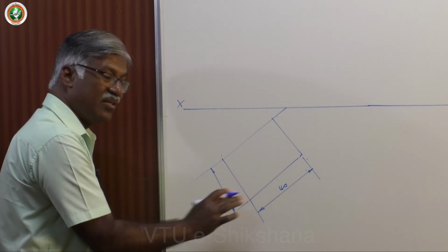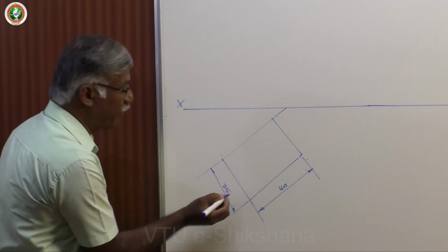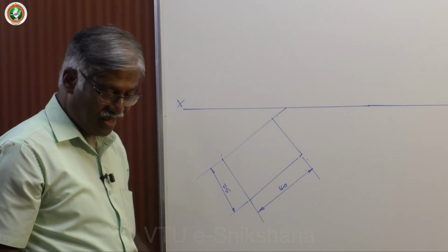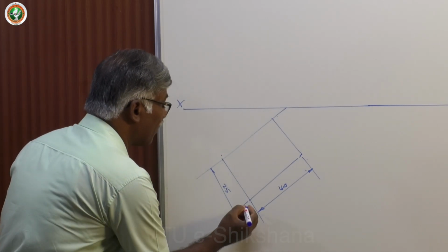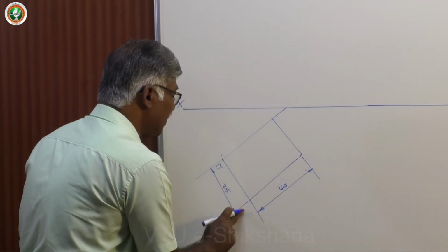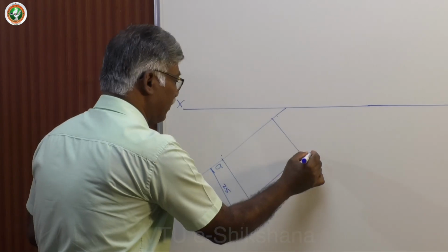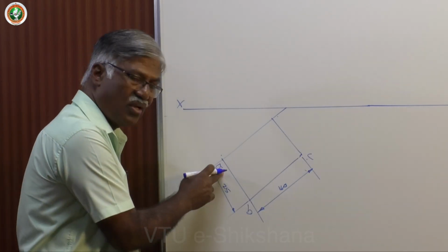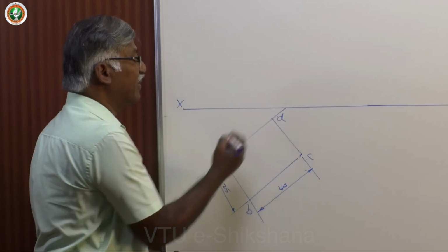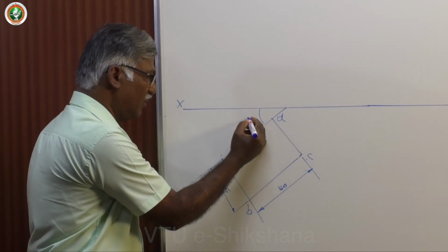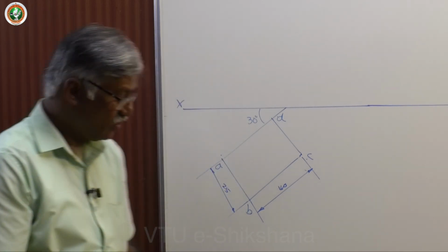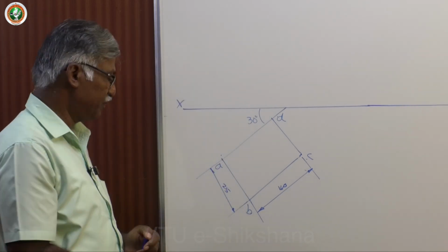See that whenever there is an inclination, this side you must keep this up. Normally if it is vertical, then only we keep to the left. Now name these points: this is A, this one is B, this is C. Why have I taken this only? This is the left extreme, the nearest corner to the observer. Normally we take that and give the inclination to this. So this is how you draw the first figure, the top view.